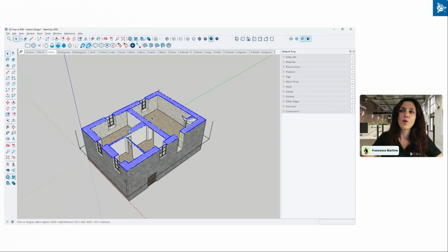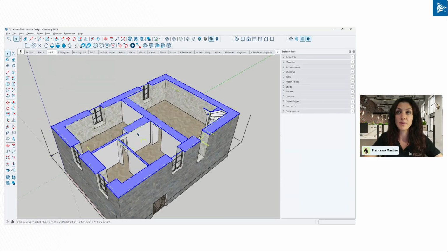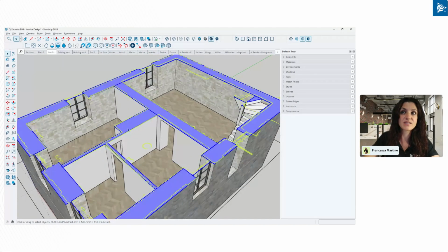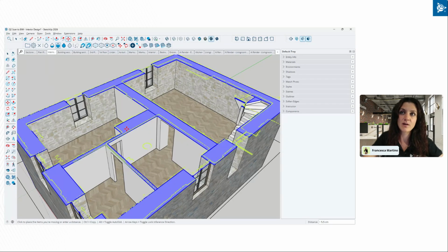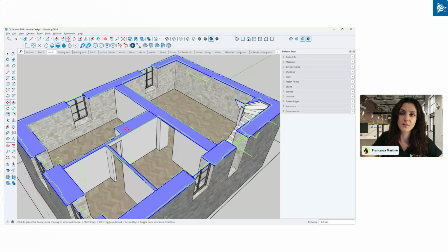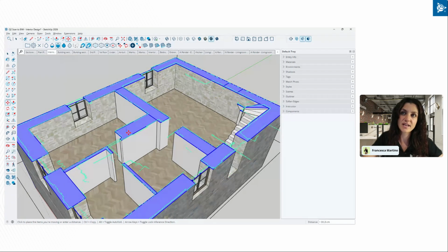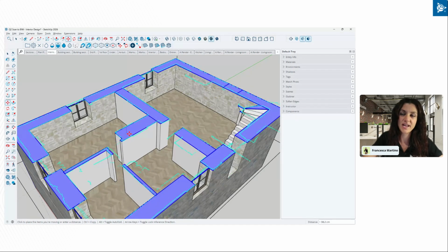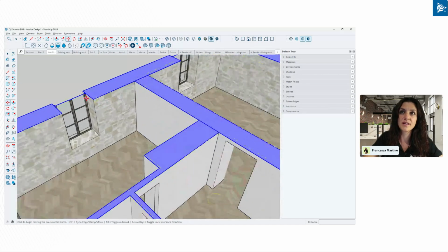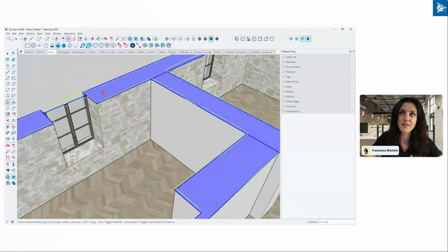Another important thing of using this technique of visualizing only the points that intersect my section cut is that I can use this as a way of verifying that whatever I actually built and modeled does correspond to reality. If I slide down this section cut, we can see that the point cloud we visualize moves alongside the section cut. And so, for example, we can make sure that in the case of this window, everything corresponds.